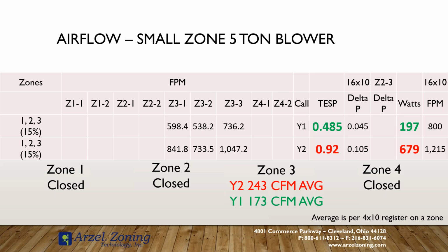But I have to be mindful that I'm not pushing things so far that I'm going to damage my equipment. So I don't recommend the Y2 blower here. I probably wouldn't want to see your static pressure getting up that high. I prefer to see it a little bit lower, closer to that 0.7, 0.8 range, not exceeding the maximum that you're going to find for the majority of equipment out there. But you're still going to maximize performance by increasing that velocity, increasing that BTU delivery.